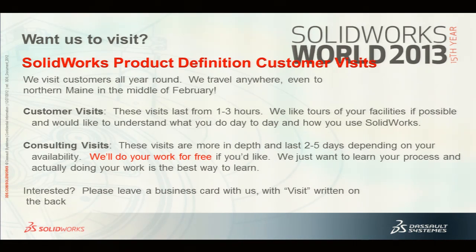Oh, and you can make an STL model solid with just your core SolidWorks, but you're not going to like what you get. Because all it's going to do is take all the faceted triangles, make planar faces, and then knit them all together and make a solid model. And you'll get the most odd-looking diamond-shaped object you'd ever want. Kind of get the picture.